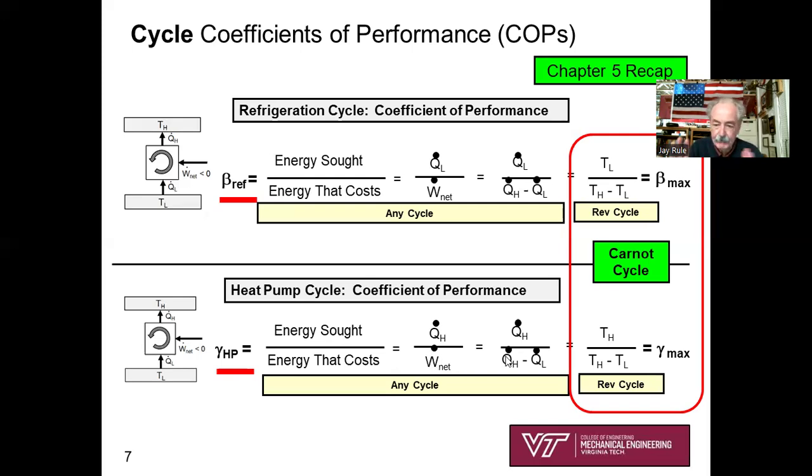So therefore, you can kind of remember for a Carnot cycle, heat pump, reversible cycle, you can look at this derivation of the coefficient of performance. And since the Carnot cycle has heat transfer proportional to absolute temperatures, you've got that the maximum possible coefficient of performance for a heat pump is TH over TH minus TL. It is my hope that you have this not necessarily in your head immediately, but you could quickly get to this out of your head instead of depending on a formula sheet.